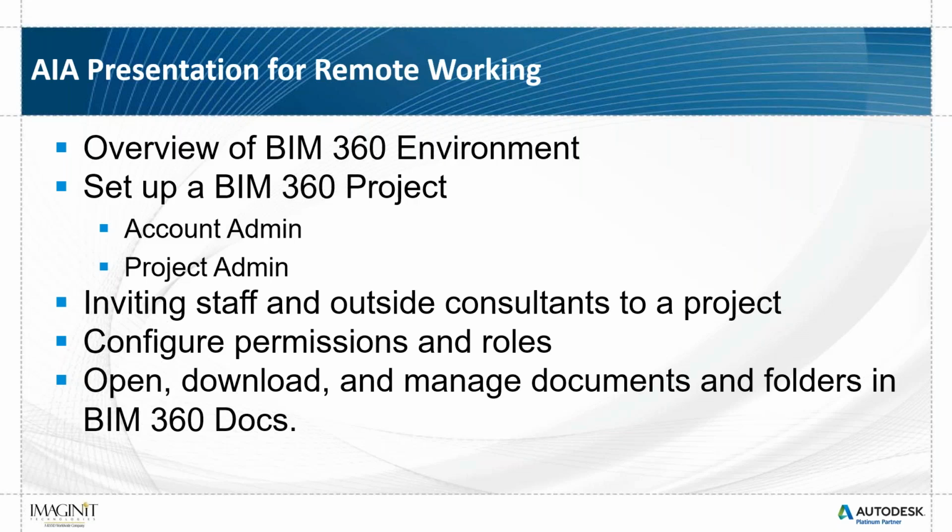So yeah, we'll go through the overview. We'll go through how to set up a BIM 360 project using BIM 360 Docs and Design. And then I'll go through some permission stuff, how to invite staff and outside consultants to projects, configure different permissions to folders and different roles within that BIM 360 hub environment. And then just in general, the workflows in BIM 360 Design, how to open, download, manage documents, both from Revit and just from a document management standpoint, okay?